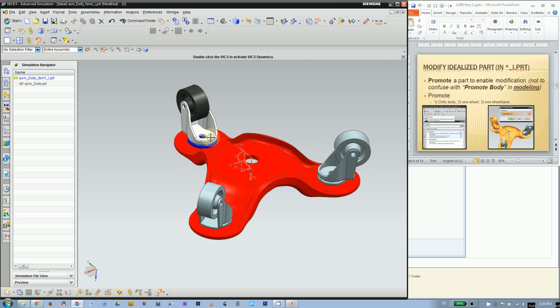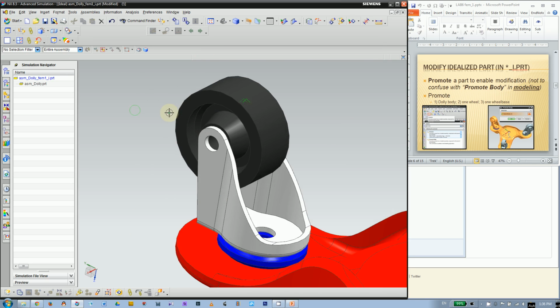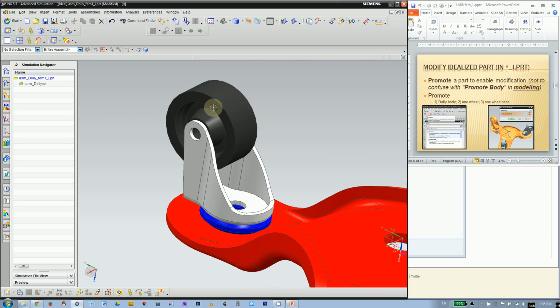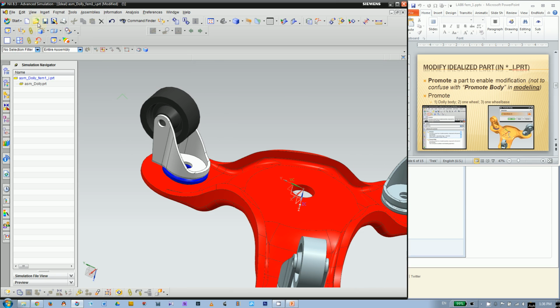So why do we only need those three? Because we can just mesh a half of this and reflect or translate to the other corners because they're all the same. Okay. So next step, for the wheel, it's symmetric, right? It's symmetric on half and half. So we can cut it into two pieces.